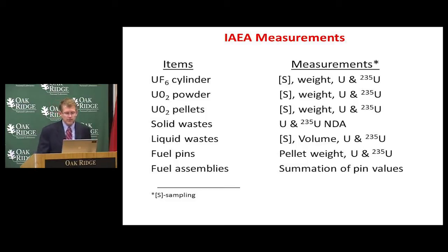For solid waste, generally you are limited to measurements of U and U-235 using NDA techniques. For liquid waste, which may be stored in tanks or accumulation columns, sometimes you're looking at measuring the volume of liquid that is there, sampling that volume to determine the concentrations.